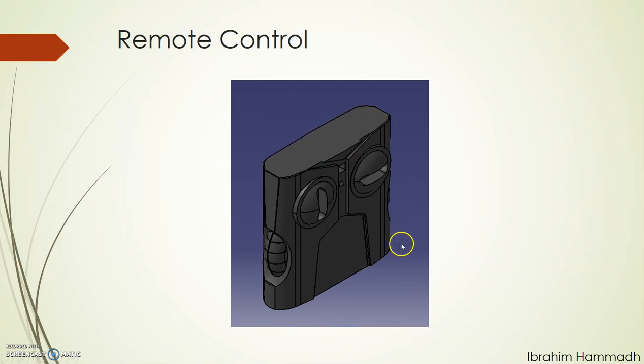it has pads that go from the base sketch all the way up to this top surface right here. Circular pads that are used to build up this feature on the side. Pocket tool that is used to make these cutouts over here. And edge fillets, as you can see, the small edge fillets over here, which were less than 0.25 millimeter, I believe.